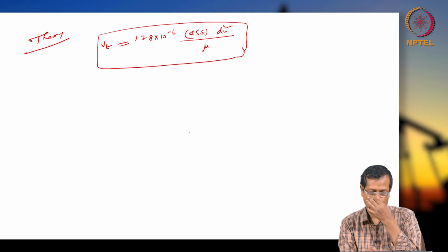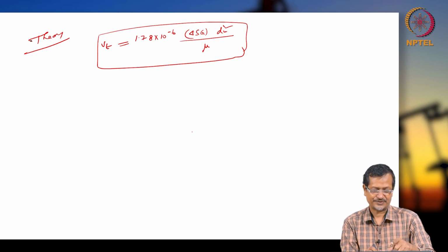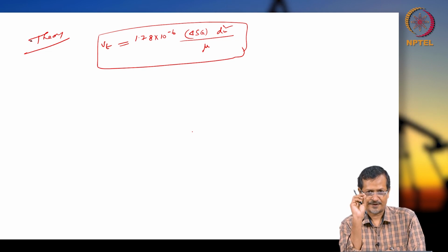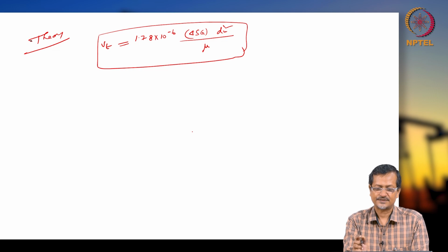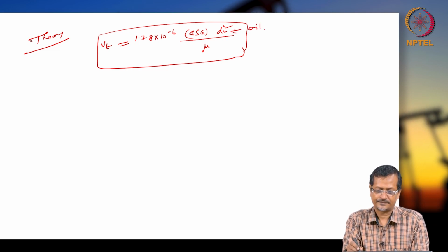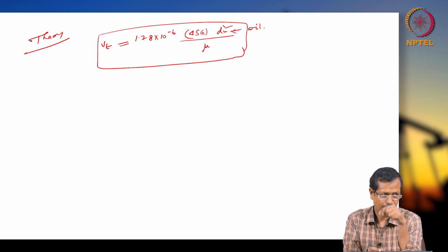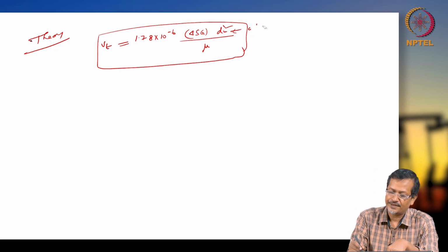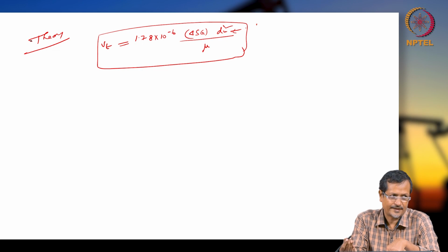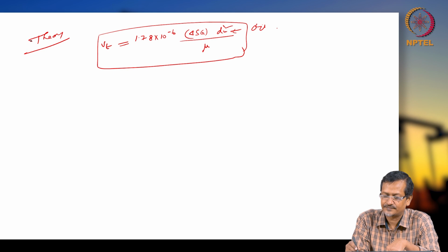Now here in the water treating system, you use the same Vt, but dm and mu changed actually. In the previous chapter, where you separated water particles from oil, dm was the water particle diameter. Now presently we will be using the oil particle diameter, the droplet.